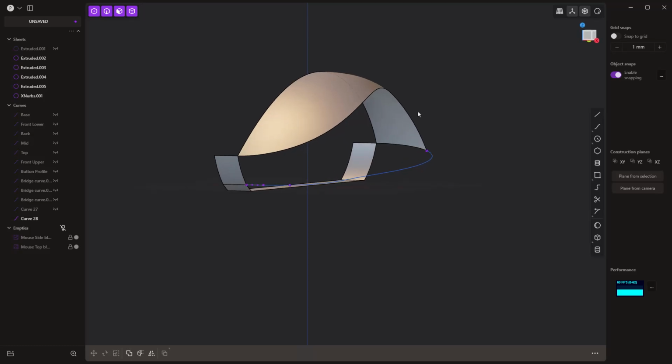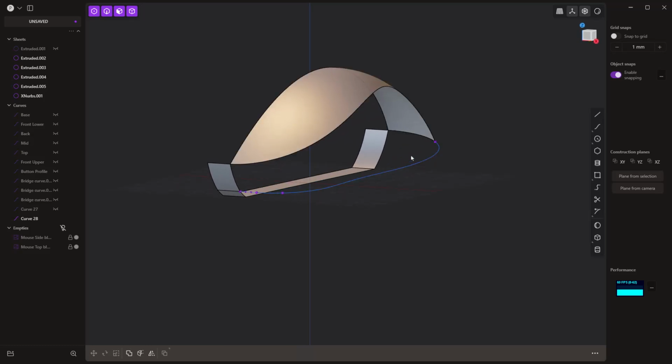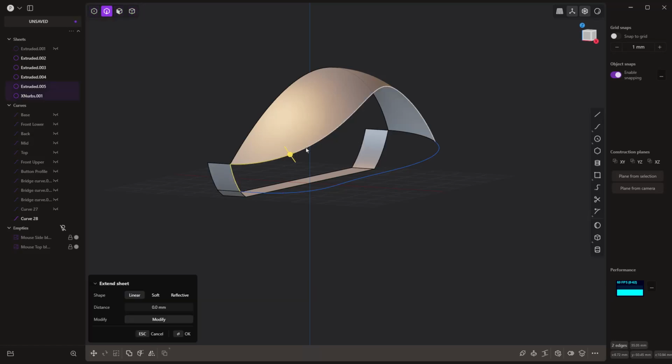So at this point, now we want to build this surface down here. This is where your thumb is going to rest on the side of the mouse. And again, it's another one of those primary or critical surfaces. The problem that we have here is there's really nothing driving the shape. So what we're going to do is go to edge selection, and let's just select all the edges around here and see what it looks like.